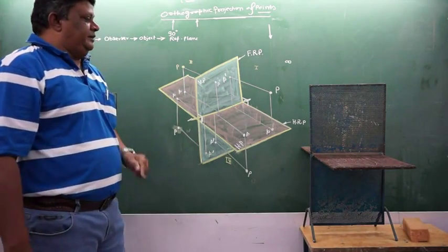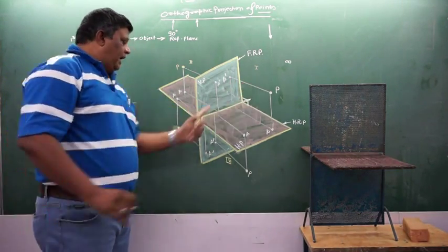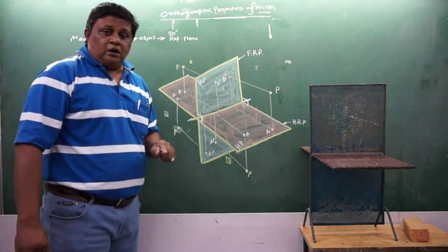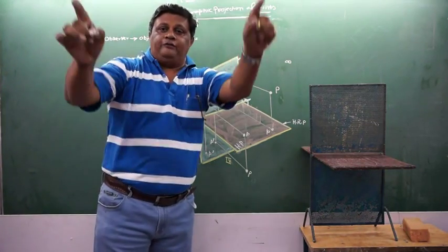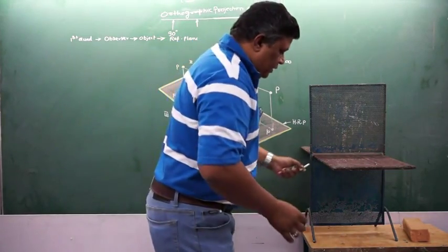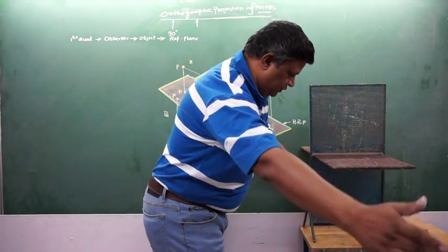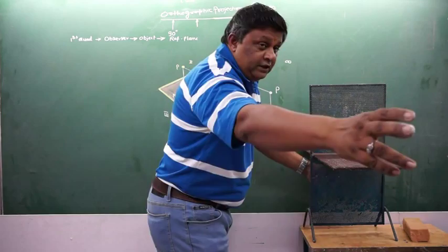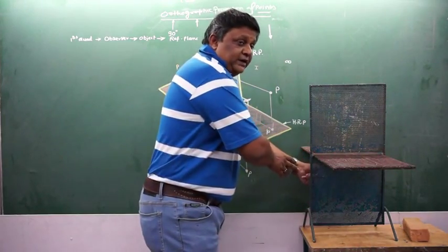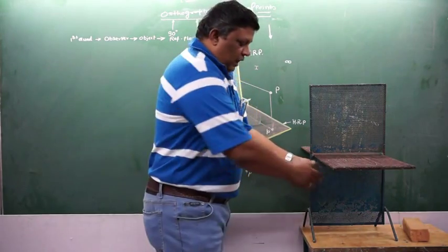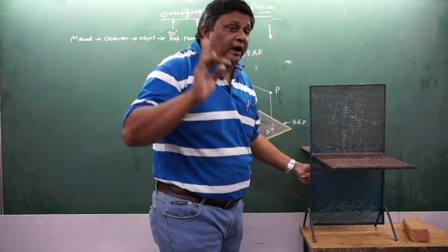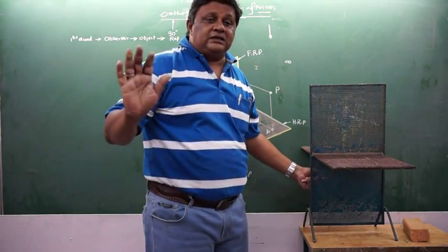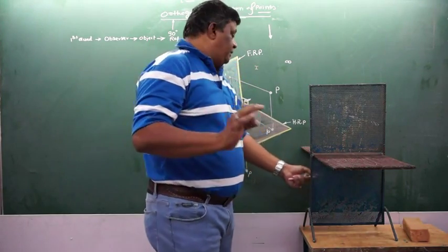Now, the drawings are basically being done in two quadrants, that is the first quadrant and the third quadrant. So what should be the equation of the third quadrant? Obviously, you being the observer, you have to be there. So, you are the observer, reference plane, and then comes the object. Observer, reference plane, and the object. Now many of you must be thinking, sir, how can we see the object? My dear friend, let me again remind you that these are totally imaginary and transparent planes.